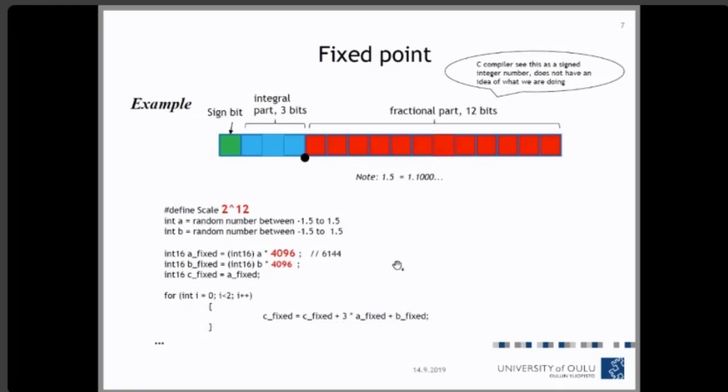But if you are multiplying two fixed point numbers, remember, the scaling factor will be applied twice. So you have to bring it back to the situation where the scaling factor is applied one time. And when we finish all operations, again we get rid of that one scaling factor as well. Also, when we have these middle operations, for example adding this to this, there can be overflow. So we have to implement some necessary shifting operations here to make sure that overflow doesn't happen.